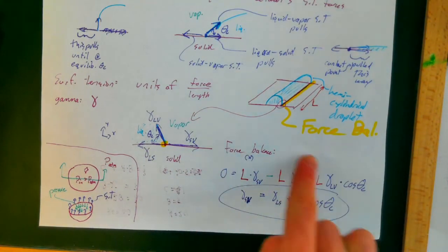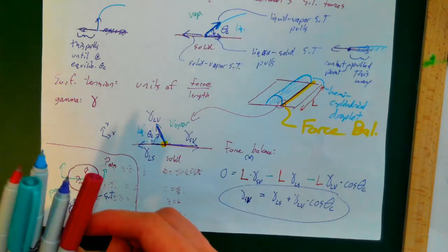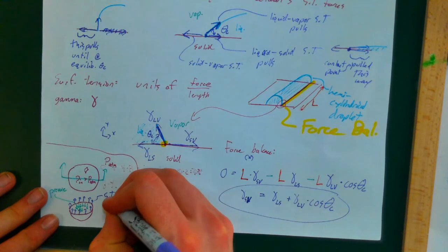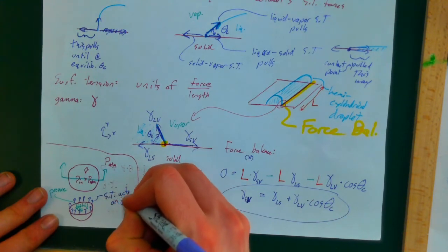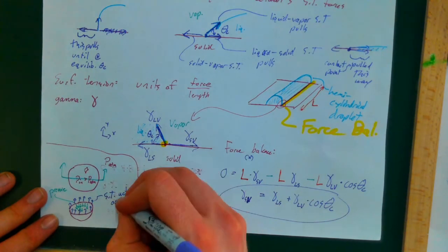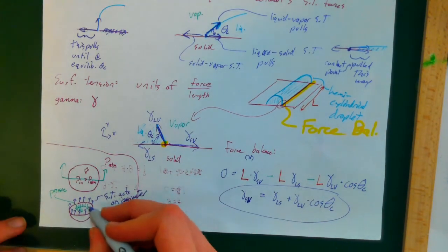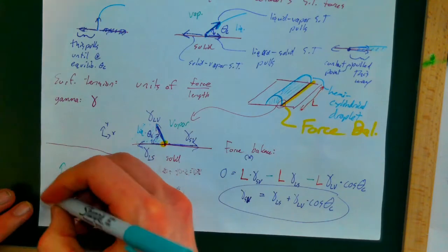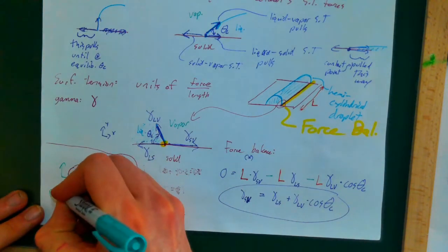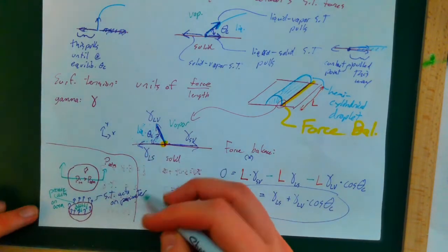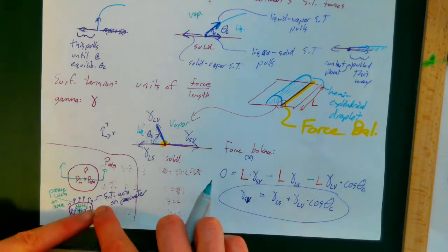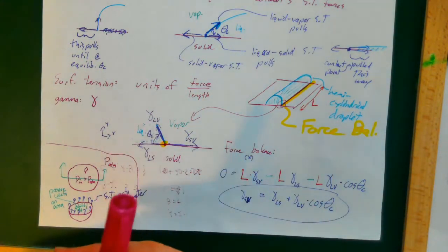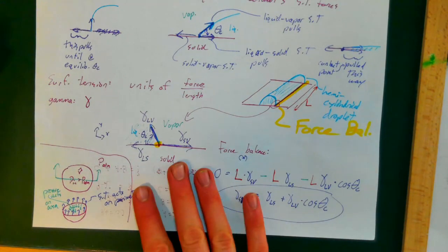And that's basically due to this idea that for surface tension, the force acts on the perimeter. The surface tension essentially acts on the perimeter of the surface here, and the pressure acts on the area, and these two are in equilibrium for bubbles that are not changing their shape, not expanding or contracting.